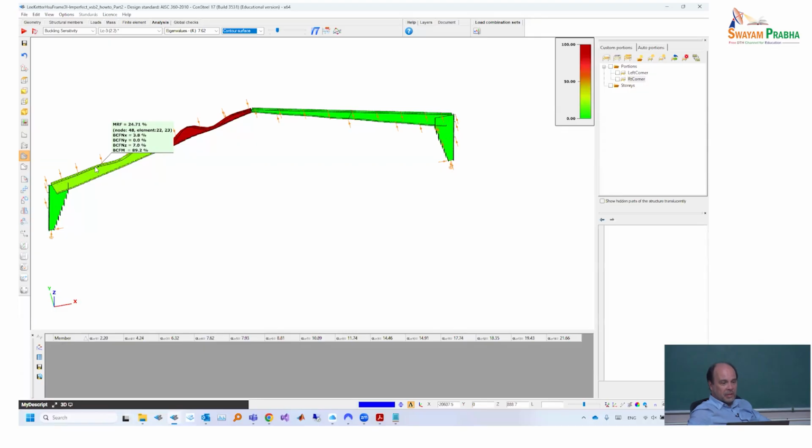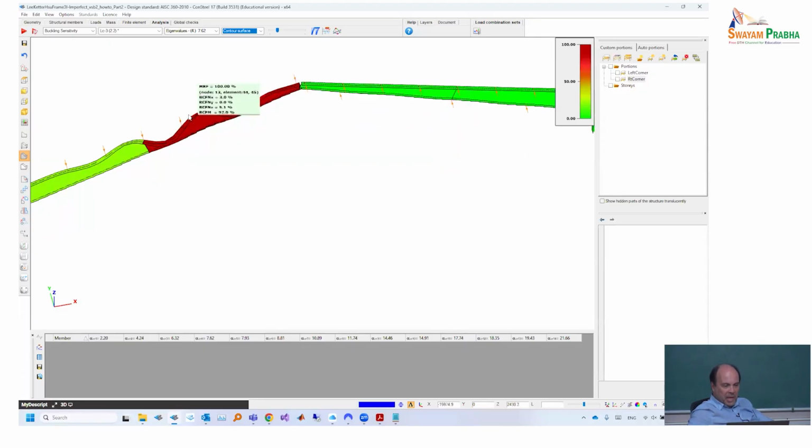24% is not 0. Based on our judgment, as this is more than 10, there is a certain danger that this could be affected. Probably it makes sense that if this part was selected, visibly the waves are continuing also into this member. So it would be very strong to say that, yes, it definitely is valid for this one, but it's definitely not valid for this one. To be on the safe side, as the 24% is more than 10%, we say that even this member will be accepted for this buckling mode.